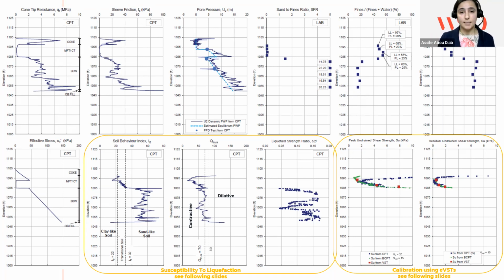And this is really very important for reclamation and decommissioning activities. And in order to be able to track this improvement, we have to look at parameters like how the fines contents are evolving and the sand to fine ratio. It really gives a good indication about the status of our tailings. And we cannot obtain these parameters unless we go and obtain actual physical samples and test them in the lab.